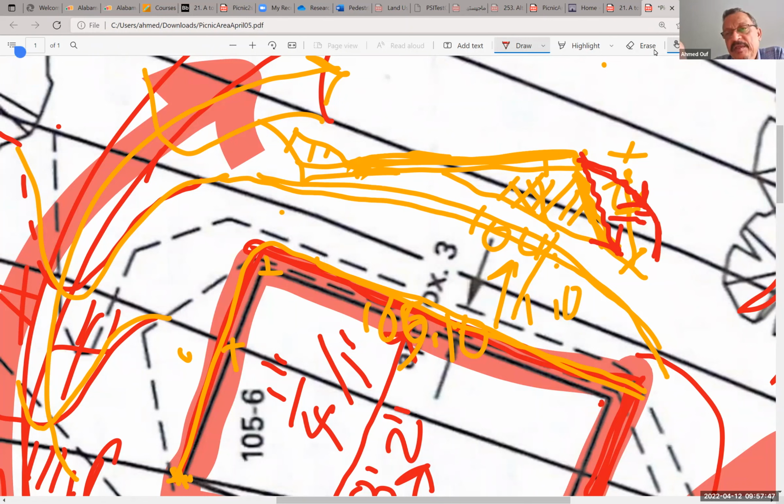Is this good enough? It depends on the situation. It depends on what's going to happen. And we said something last time that I would like to remind you of. We said that if you want to have grass and mow it, it shouldn't be sloped more than 33, 34%. What does it mean? It means that in every 3 feet of distance, you have 1 foot of drop.